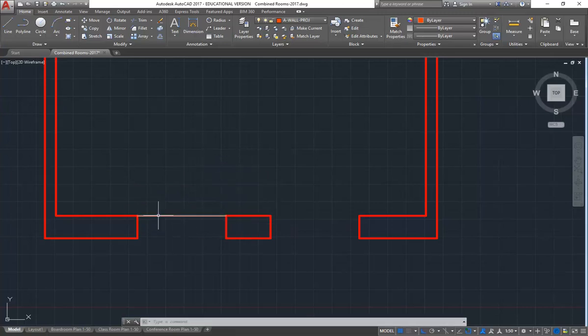Okay, so notice how now that line already, if you're used to reading architectural graphics, reads as being lower than this line because it's lighter. If you're not reading it that way, that's something you need to train your eyes and your brain to recognise: heavy means in the foreground, light means in the background. So all of these lines inside the opening are below the cut plane.